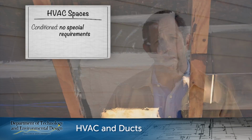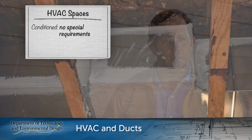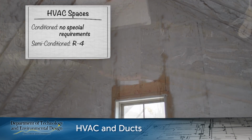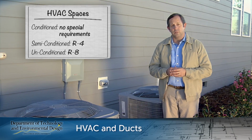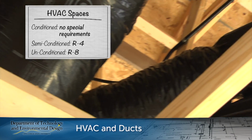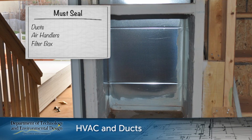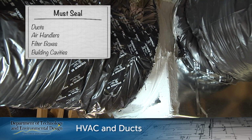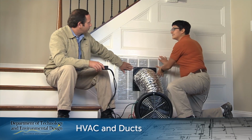As you also probably know, there are 3 considerations for duct insulation. In conditioned space, where AC and heat are always available, no special insulation is necessary. In semi-conditioned spaces, such as closed crawl spaces and sealed attics, R4 is required. But unconditioned space, such as vented crawl spaces or unconditioned attics, requires R8. All ducts, air handlers, filter boxes, and building cavities used as return ducts must be sealed. All right, all sealed? Great.